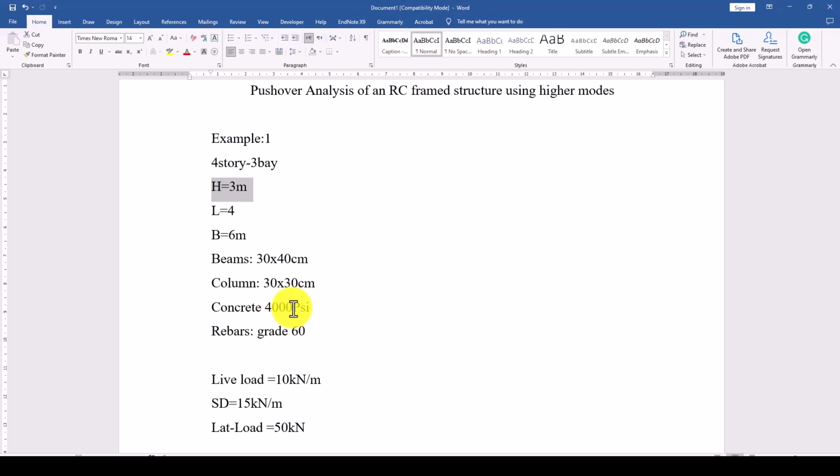I should say the pushover analysis is always conducted for assessment of existing buildings. So it means we will do the analysis to see how the structure responds, how the structure performance can be evaluated based on the target displacement, or considering the mode shape of a structure. So from all these things, we understand the structure should be designed, even exist in the field, on the site, and then we will evaluate the structure's earthquake response.